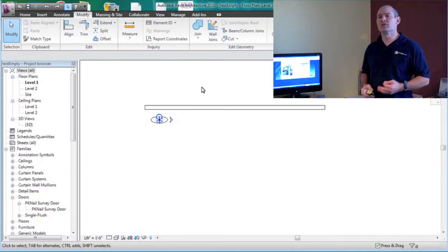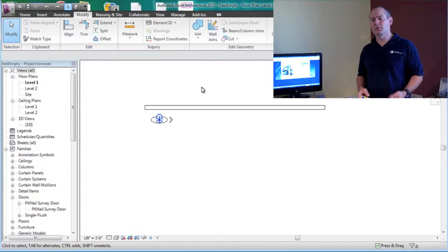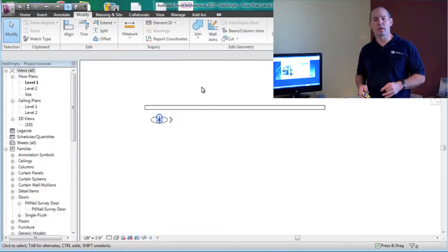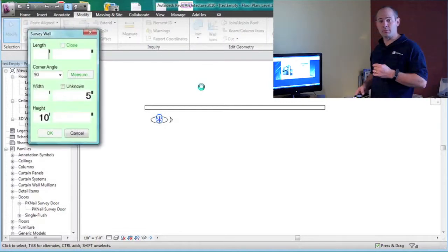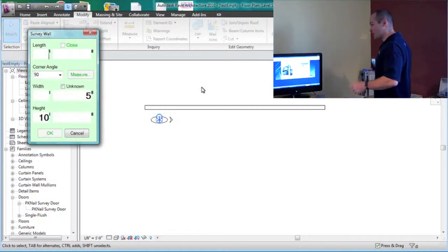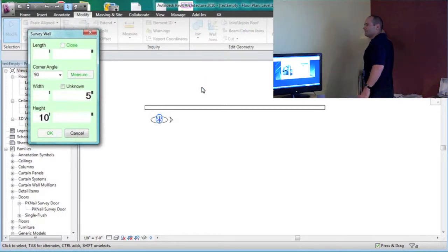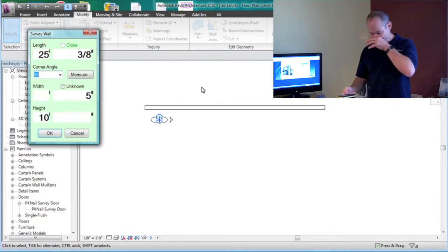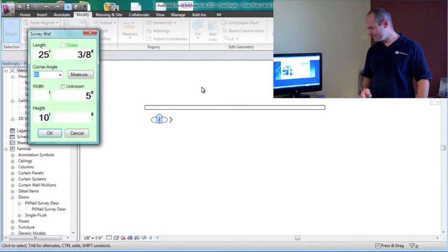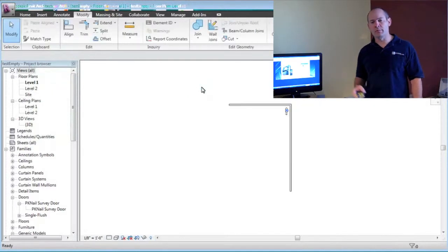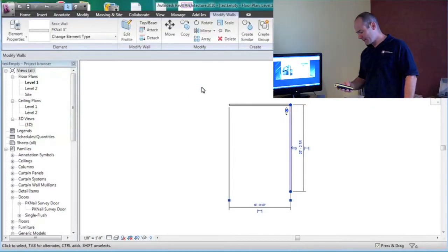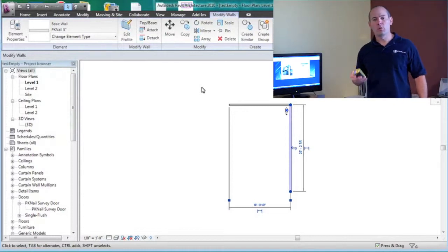The first thing you need is two known points, and in this case we're going to use the endpoints of a wall. The first thing I'll need to do is open up the Add Wall dialog box in PKNail and measure this wall. I'll input it, add it, and those two endpoints will act as our reference points in order to triangulate. Next wall will be an angle wall.